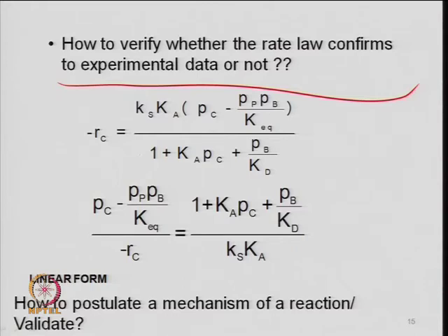So, the rate of reaction, I said, is given by something like this. From experimental data you have made certain analyses: the effect of partial pressure of each component, the temperature effect, the space time effect, and then you measure this rate. Now, this rate is to be verified from your experimental data, because this is simulated, theoretical data analysis. So, now you have just linearized; this is one method of linear regression, or non-linear regression methods, when you have just R equal to k p a to the power n.